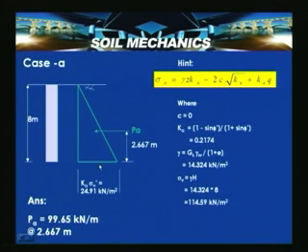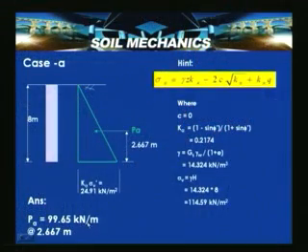So these retaining walls are generally considered as perimeter length walls. The active earth pressure thrust units are kilonewton per meter. Suppose the wall is about 5 meters long, then the total earth pressure thrust acting on the wall in the active case can be calculated for the given length. But generally these are considered per meter length, being continuous plane strain structures, and we get the thrust per meter length. So here in this case please note PA is equal to 99.65 kilonewton per meter, and it is acting at h by 3 from the base, that is 2.67 meters.